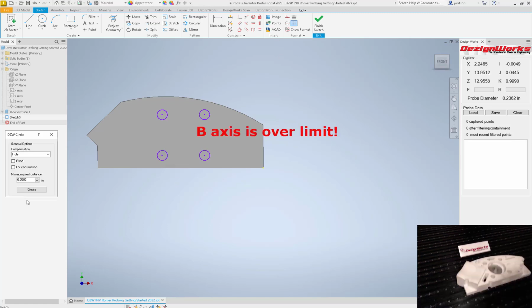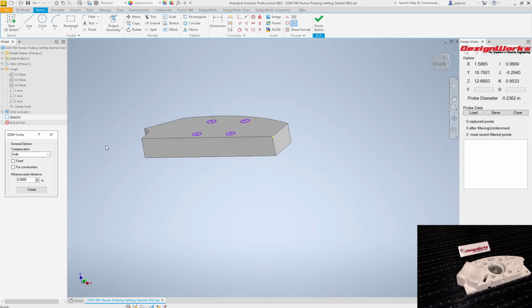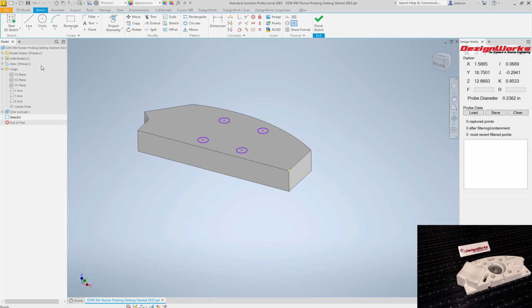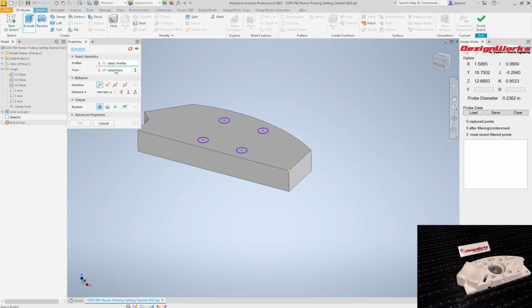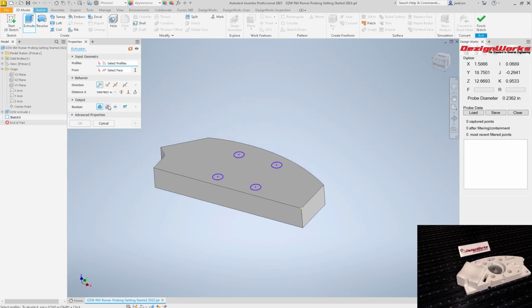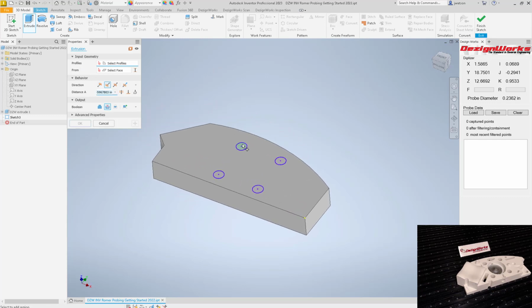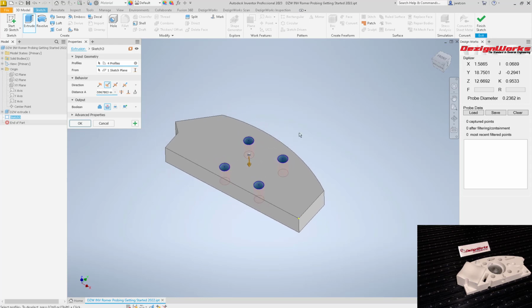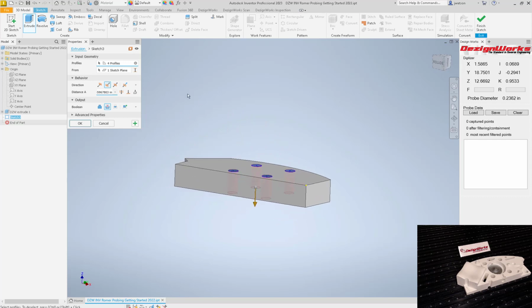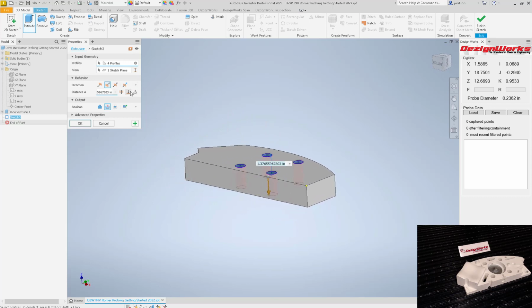So once you have that, you can do this 2 different ways. In this case, I know I want through all. So you could actually do this. Come up to Inventor, 3D model, extrude, and I want to do a cut. Move the mouse down here to one of these, or actually it'll find them. Just like you do if you drew this. And you could tell it through all or whatever you want to do.